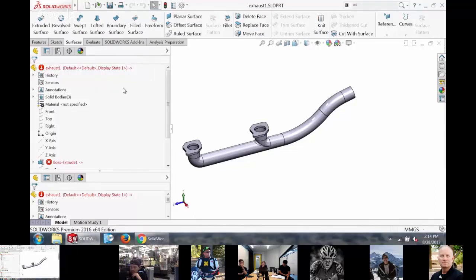Basically, you want to take external references out before you give it one of those revs, one of those revs has approval. When you're in an R&D phase and you're just prototyping and making different changes, it's great to have an external reference because things will always fit inside. In this case, what's going on is the exhaust tubes fit right up to the bottom of those cylinders because they were designed from the bottoms of those cylinders. And at this point, if I make the cylinders further apart from each other, the exhaust pipe should update because it's got that external reference.